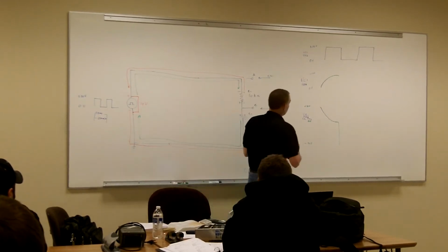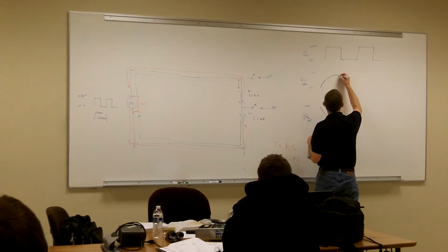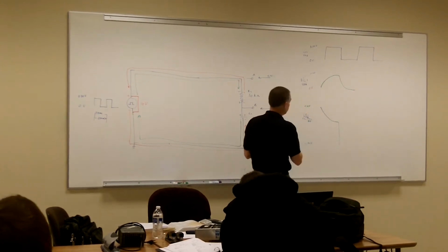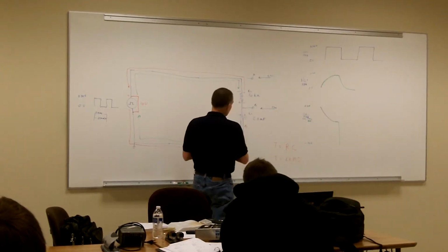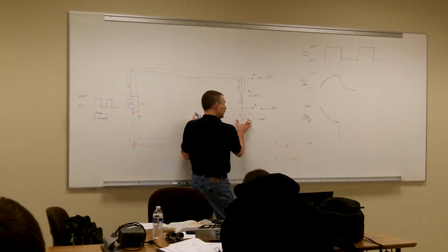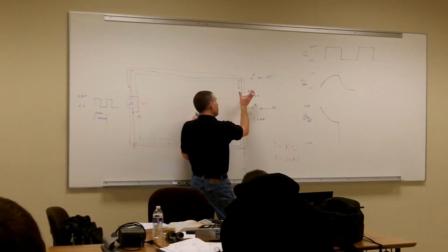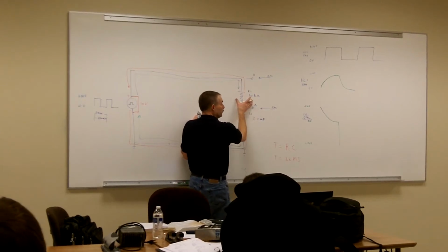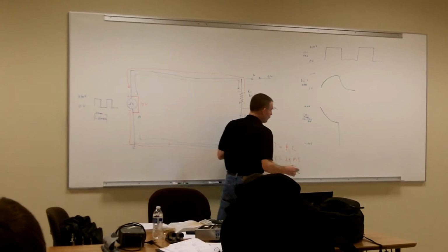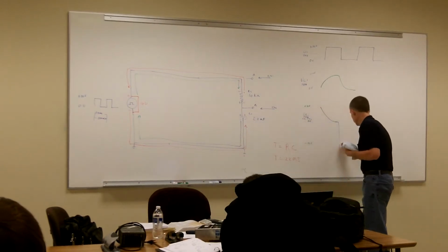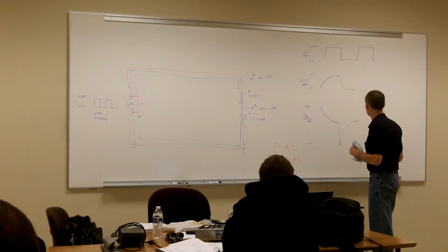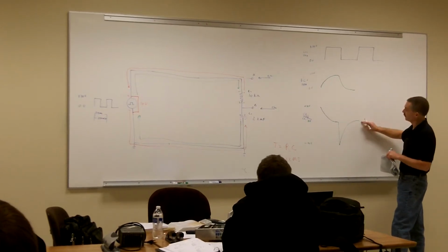So that capacitor is going to start to discharge, and after 5 time constants, it drops down to 0 volts. So as this capacitor starts to discharge and the voltage starts dropping across the capacitor, so does my voltage across my resistor. So now my voltage across my resistor is going to start to go back to 0 volts.